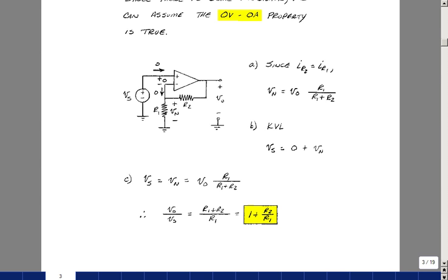The reason it's called a non-inverting amplifier is that the gain here is positive, but it's really, once you've looked at the inverting, that would make sense. So the inverting amplifier had a minus sign. That just means that if you had a sine wave input, the minus sign would flip it over, it would invert it. Same is true for any other wave shape.